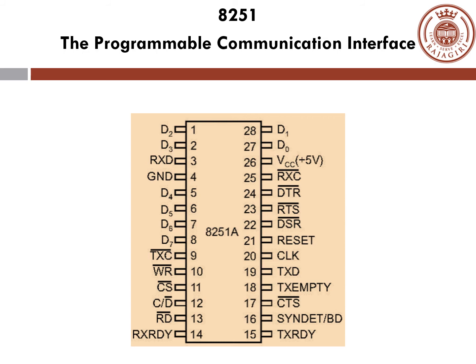Any programmable I/O device will have a control register to which the microprocessor can write an instruction, a status register that can be read by the microprocessor unit, the I/O buffer or register, some control logic, chip select logic, bidirectional data bus, handshake signals, and interrupt logic.